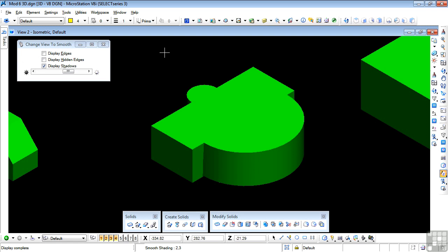And since you're using AccuDraw to supply that distance dimension, you can enter a distance value in AccuDraw for the face offset, or use the distance value in the tool settings window. It's also quite possible to snap to other elements for the distance value, but you need to think carefully about the drawing plane orientation and the snap points. Sometimes you'll see a note in the status line saying "unable to move face." This is MicroStation telling you that the tool cannot do what you're asking it. An example of this is if you try to stretch a face above the level of other faces, sometimes MicroStation will refuse to do this. We'll see an example of this as we proceed.